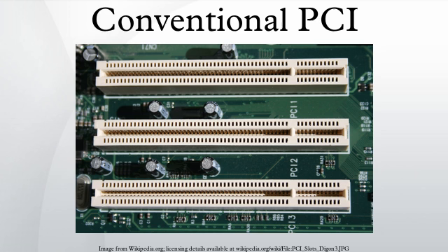64-bit PCI extends this by an additional 32 contacts on each side which provide AD[63:32], C/BE[7:4], the PAR64 parity signal, and a number of power and ground pins. Most lines are connected to each slot in parallel. The exceptions are: each slot has its own REQ output to, and GNT input from, the motherboard arbiter. Each slot has its own IDSEL line, usually connected to a specific AD line.